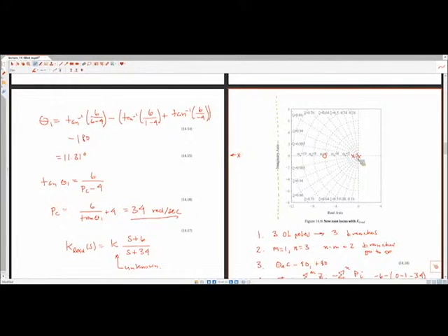We have that the root locus on the real axis is to the left of an odd number of poles and zeros. So over here, it's to the left of 0 poles and zeros, and here, to the left of 1 pole. Go over this pole, I'm to the left of 2 poles. And I go over this zero, I'm to the left of 2 poles and 1 zero, which is 3. So that means that the root locus lies in between here as well.